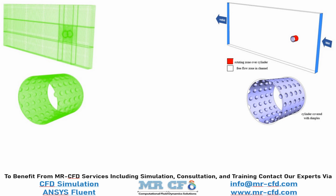The geometry consists of a rectangular channel with a cylindrical object inside as a rotating object, and a cylindrical space around the rotating cylinder inside the channel is distinguished. Also, dimples or protrusions have been created on the surface of the cylinder, which has a roughness ratio of 0.5, called the ratio of the depth of the dimple cavity to the diameter of the dimple.